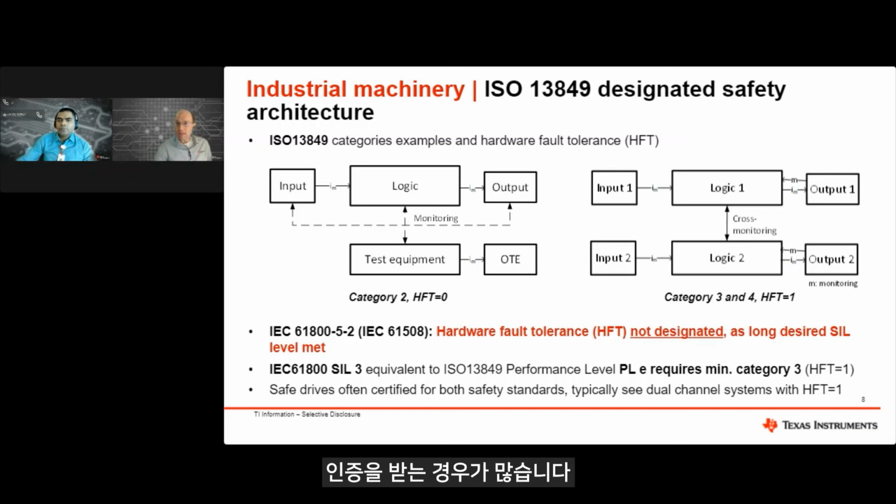One of the key collateral offered for the microcontroller is the customizable FMEDA. This can be tuned for the end use cases and a variety of safety concepts. This is what a typical C2000 MCU FMEDA looks like. It is organized in multiple tabs in the spreadsheet. As you may have already noticed, each tab has a distinct color, mainly blue and green.